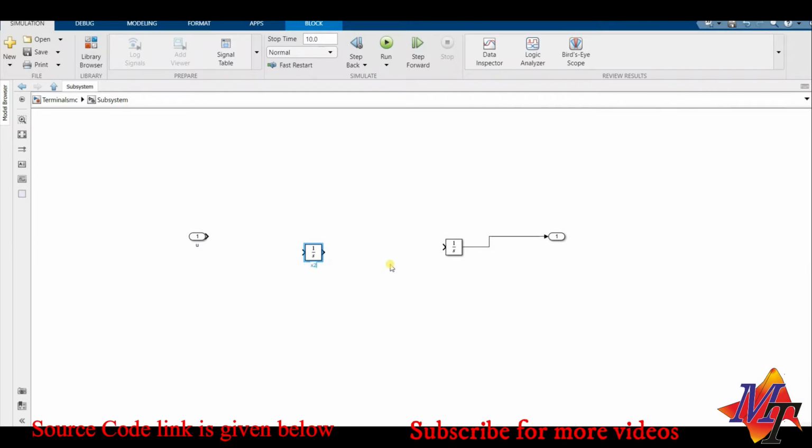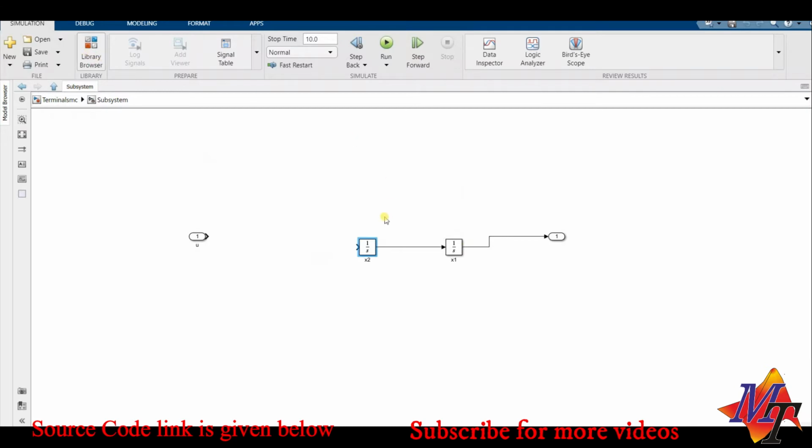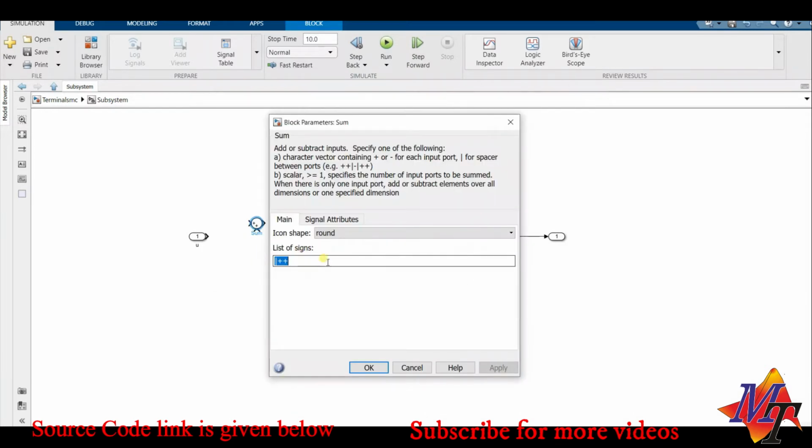This we get here as x2, and this here we get is x1. So using system equations, we know x1 dot is equal to x2, but x2 dot is equal to some function of x2 and 0.1 sine 20t plus u. So for that we'll need a sum block which has three components to be added.